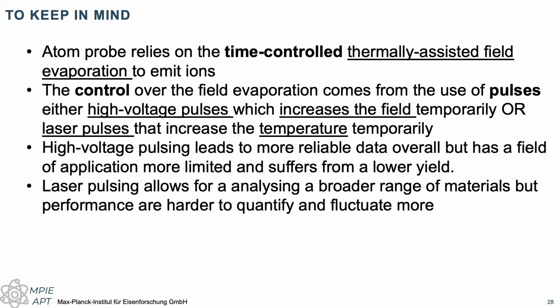I must say that I tend to be a bit fed up with people telling me, oh, but I use the same analysis conditions as in this paper. And actually, it means nothing because if you take 40 picojoule as a laser pulse energy one day and use the same laser pulse energy the next day, the peak temperature that you're going to reach for two different specimens is not the same. So I hope this triggers some thoughts in your head,